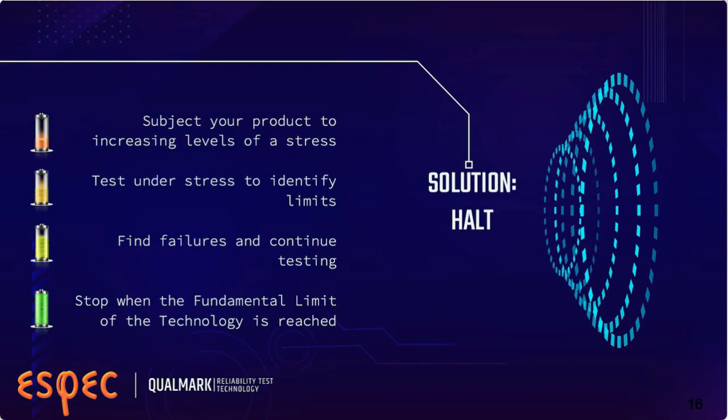And we step through the stresses, going from least destructive to most destructive stress. So we start with thermal stepping, cold and hot. Then we do rapid thermal, going back and forth between the limits we found in step testing. Then we do vibration at ambient. Then we do combined testing. In all cases, we're testing under stress. That is, the product is being functionally tested while it's in the system, while it's undergoing those stresses. That is critical to finding the soft failures that go away when you take the stress away and wind up turning into no defect found failures from the field.